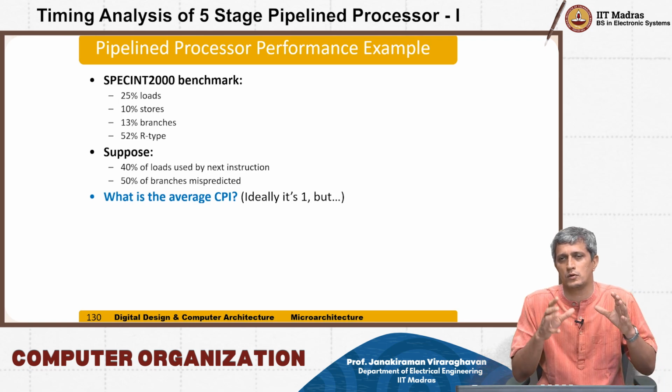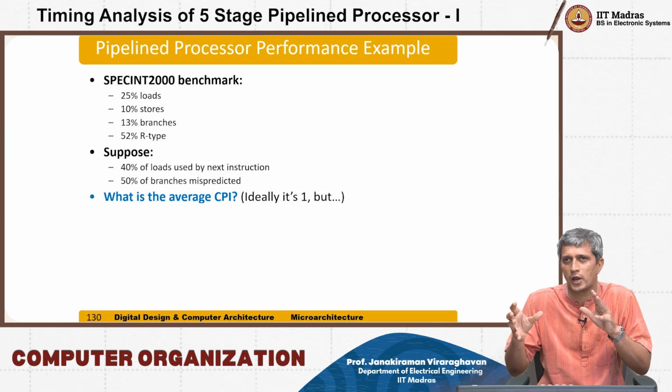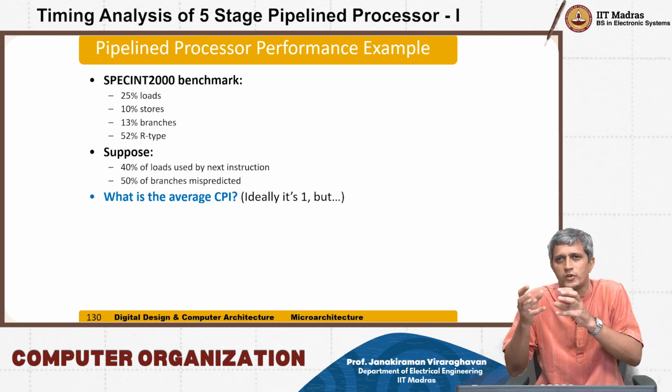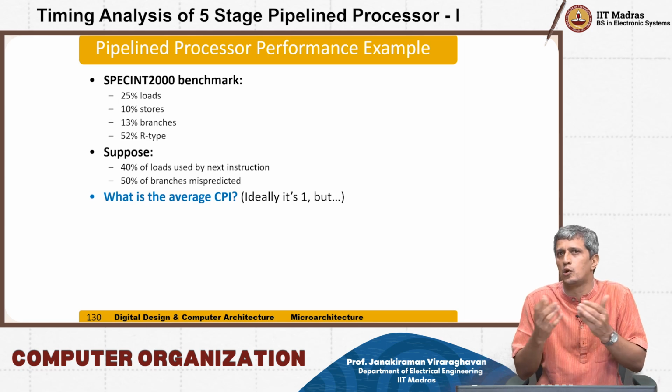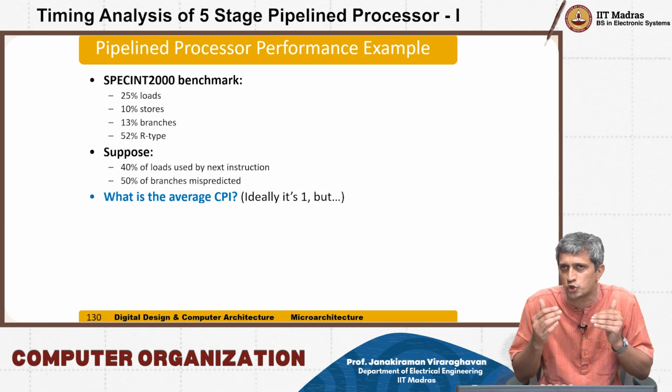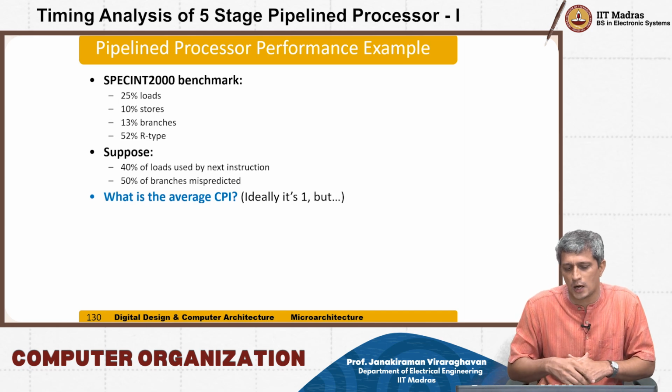Remember that with register forwarding, we were able to prevent stalling of the pipeline significantly for a lot of cases. But for the load word, we had no choice, we had to stall the pipeline, right?